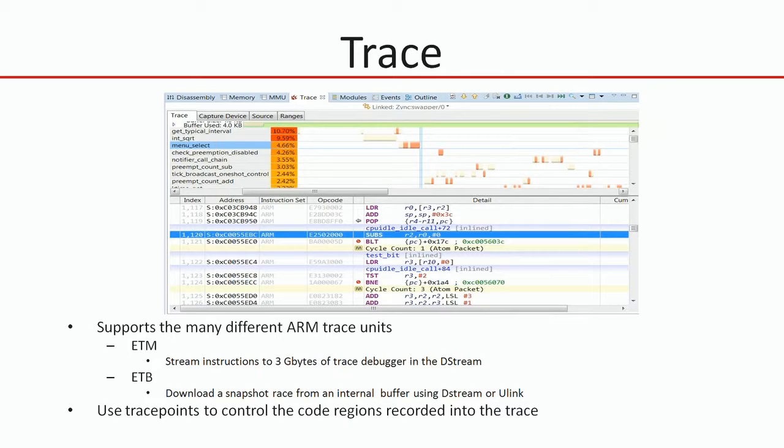There's also, within DS5, a CoreSight library. So once we have our application code developed and we're ready to deploy our product, the CoreSight library can be included, and this can be used to configure the CoreSight debug architecture on our product, so that if in the field we encounter some problems, we can use this as a sort of crash debug system, so that you can log all of the trace activity to a file and then download this and replay it in the tool.